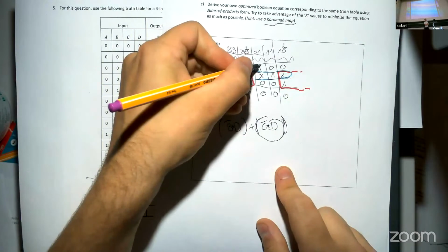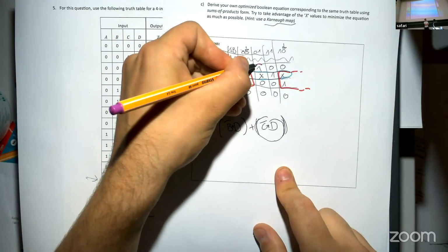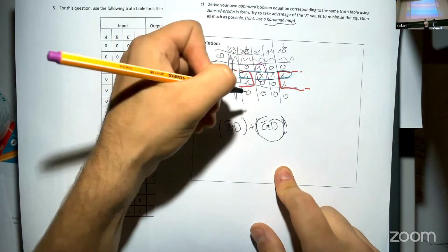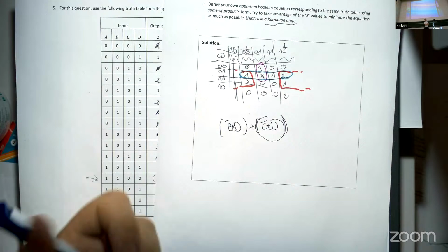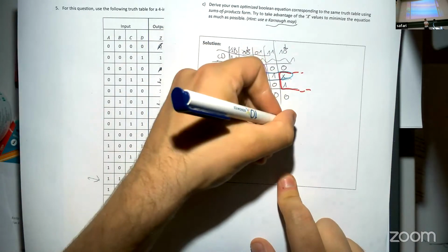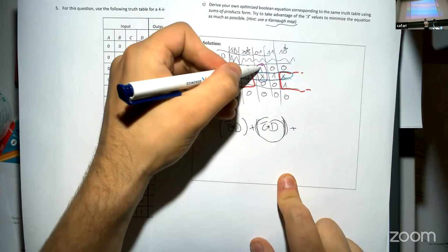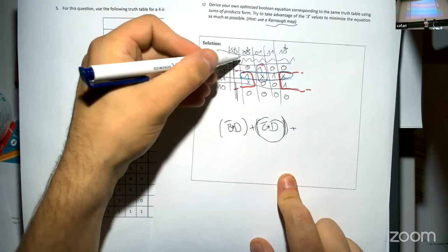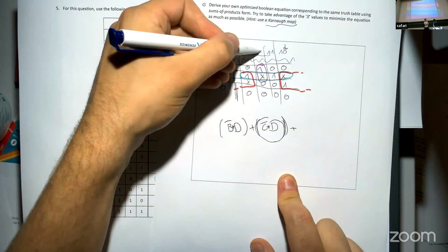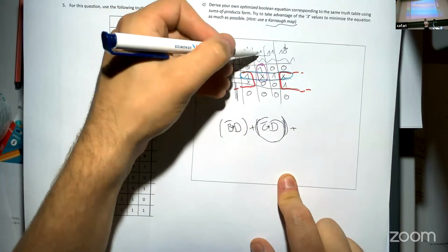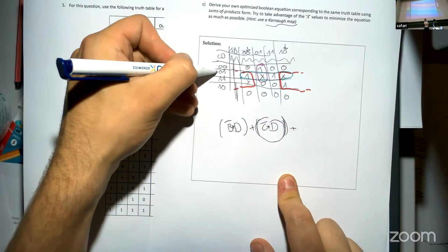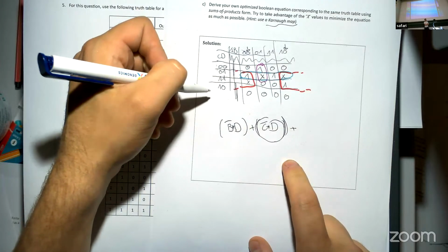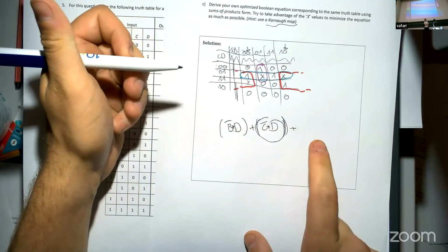And now what's remaining here is just one more term. But ideally, you pick these squares as big as possible. That means you write fewer letters in your equation. So, if we just needed to cover that one, we could identify it by exactly 0, 1, 0, 0. But if we identify it by having 0, 1, and either of these two lines, we have more degrees of freedom and one letter less over here.